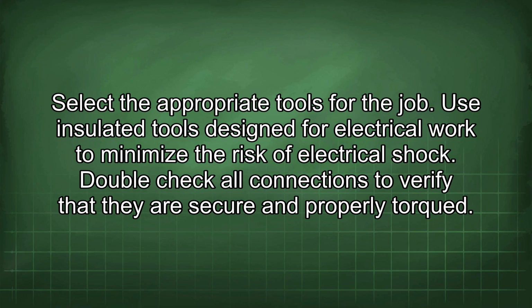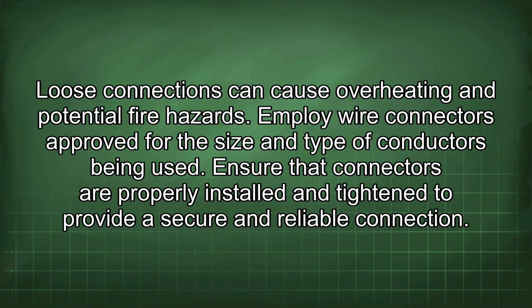Select the appropriate tools for the job. Use insulated tools designed for electrical work to minimize the risk of electrical shock. Double-check all connections to verify that they are secure and properly torqued. Loose connections can cause overheating and potential fire hazards.